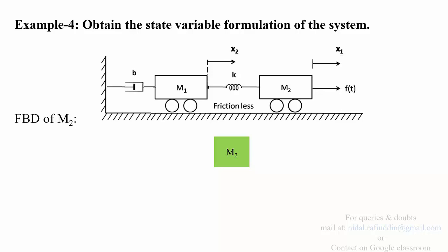So it's important to know how you are going to implement the state variable representation for a system, and of course you are going to find different variables implemented in different ways. But if you understand the essence of how you obtain the state variable formulation of a system, then you can interlink all of them easily. Shown over here is an example again for a mechanical system comprising two masses.